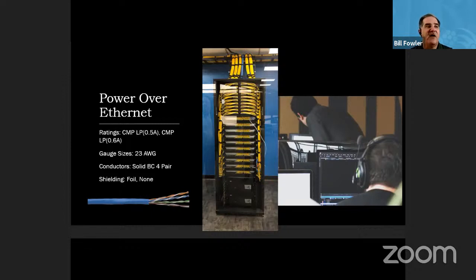So they found that now with twisted pair, we had a pair that was not being used. Typically the blue pair was used for communication, phone guys, and originally starting out, that's the pair color they used because that was a center pair color. Then when Ethernet 10-Base-T came along, I hate to say it, I was there when it was ratified, 10-Base-T is a signal, but they used the orange and the green pair for transmit and receive, so we needed 2 separate pairs. So that left a lonely brown pair by itself not being used.